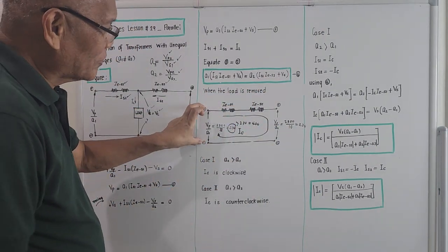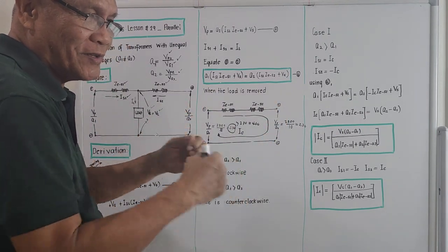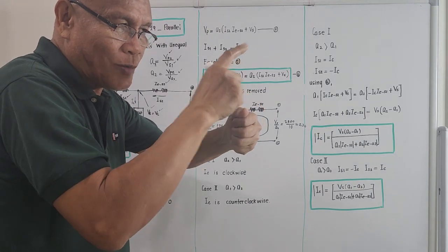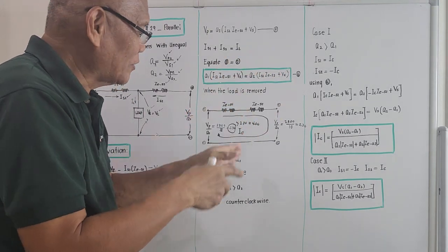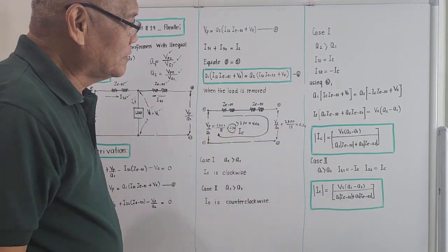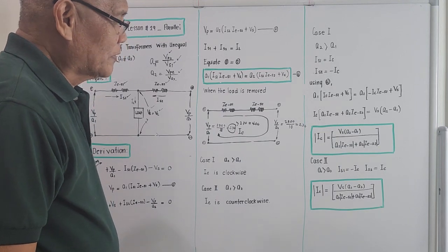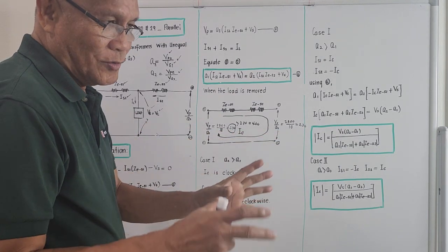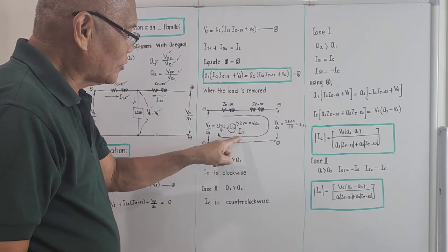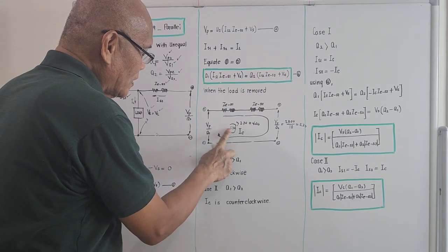This is stronger than this one, so whether we like it or not, there will be a net voltage, right? 400 and 230, they will try to fight each other. There will be a difference of around, how much? 230, 170? It's 170. So that difference in voltage will produce a current, and that current is actually the so-called circulating current. I will try to erase this one.